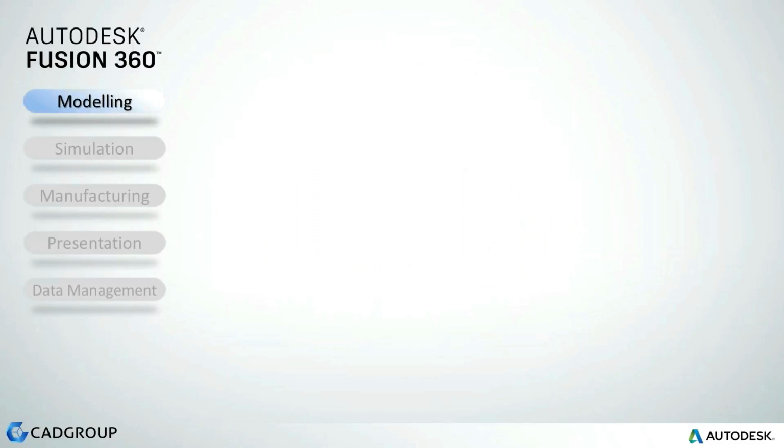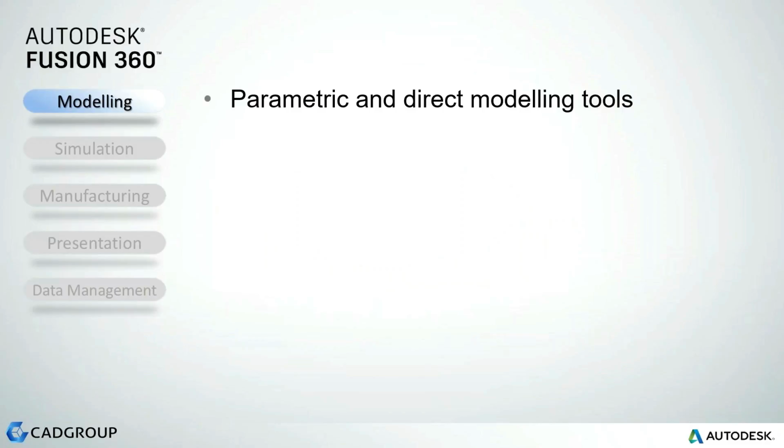All right, let's have a look at modeling. Fusion 360 combines both history-based parametric modeling and direct modeling, where you can define the model using traditional feature-based tools and then enhance this with on-screen push and pull techniques. There's also free-form modeling in Fusion 360, which uses T-spline technology, and you can use this to create and modify complex subdivisional surfaces, so that you can create forms that are more organic looking and more ergonomic.